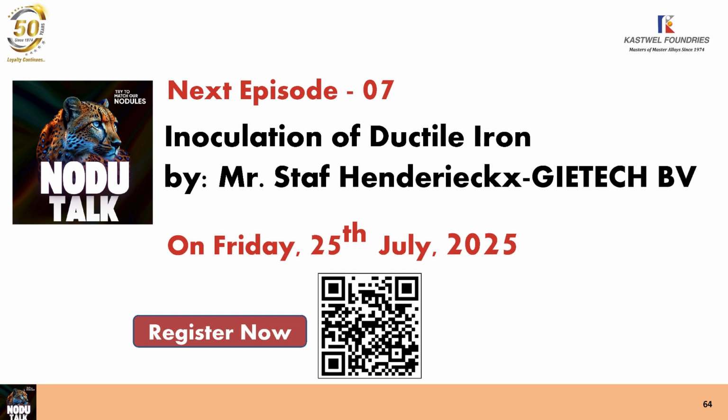And the dross of the first metal, which is still there, should float up to the top of the casting so that it disappears in a slag holder or in the risers. Or you must make sure that your first metal does not enter your casting. You should bring it somewhere where it cannot enter your casting.